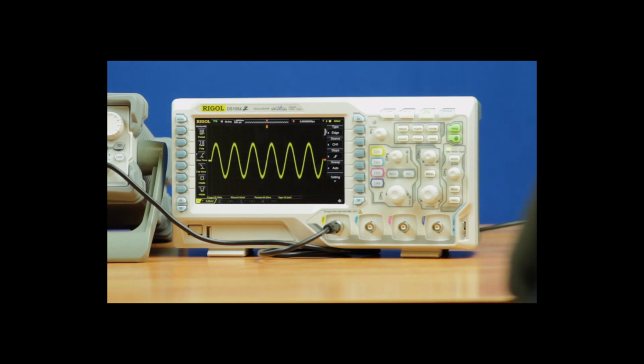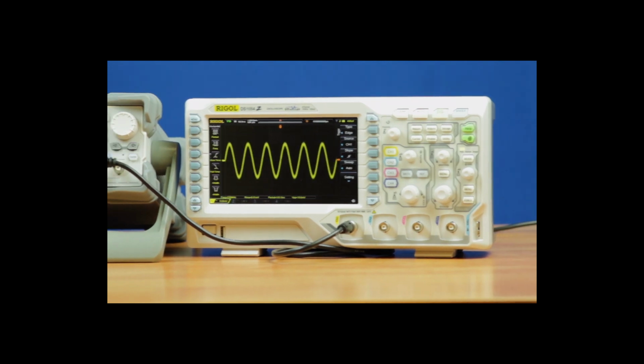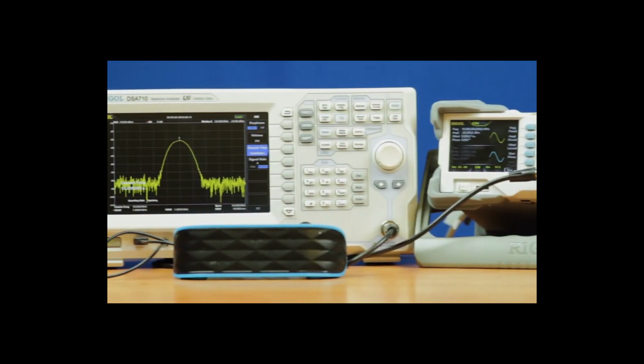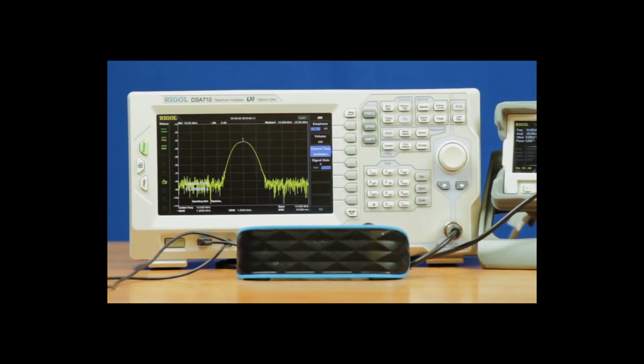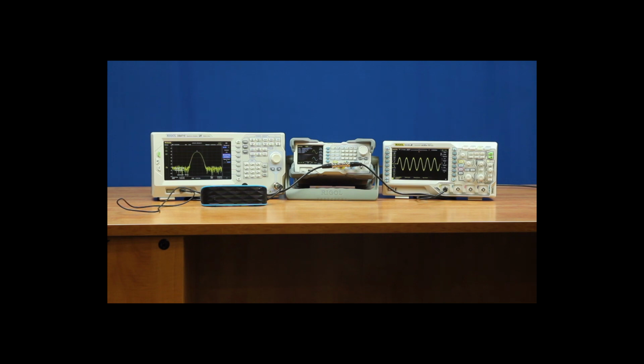The spectrum analyzer is set up to do 10-second chunks, so the display doesn't change, but the audio comes out continuously 10 seconds at a time. So that's how we really set up a basic analog modulation scheme to modulate the amplitude, bring it across the spectrum analyzer, and demodulate it.